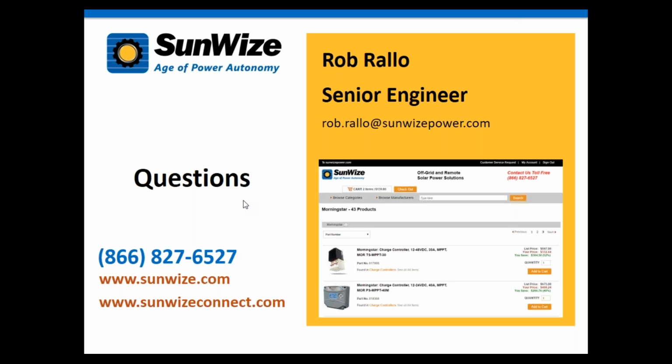So from the other cells that still have sunlight on them, they're still producing current. Now you have these shaded cells that are going to want to take current. So the current from the sunlight is going to go into the shaded ones. To prevent that from happening, those bypass diodes end up activating. Okay, so the voltage over them, the forward bias voltage over them shifts, and it causes them to basically activate, and it causes the current to go around that section.